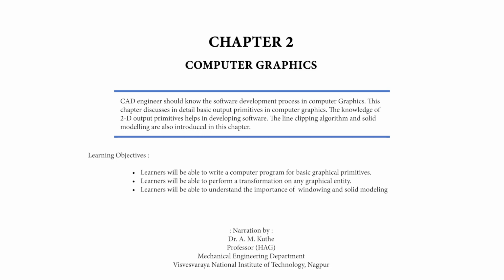Number 3, creation of a wireframe model is lengthy in terms of the amount of defining data and command sequence. Number 4, both topological and geometrical data are needed to construct wireframe models. Number 5, wireframe models cannot be used for cross-sectioning, interference, etc. Number 6, models of complex design having many edges become very confusing to understand and interpret.